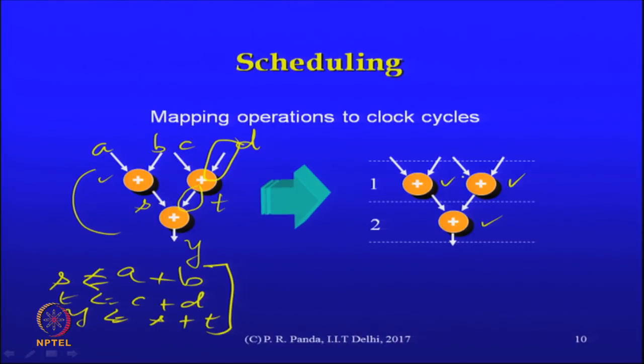So, same clock cycle means that the operations are being performed in parallel, and therefore, you need access to two adders in order to realize that circuit. Okay. So, somehow that resource constraint was available to the scheduler, that is why it took that decision. But what if it had 3 adders? Could it have scheduled all the 3 into the same clock cycle?